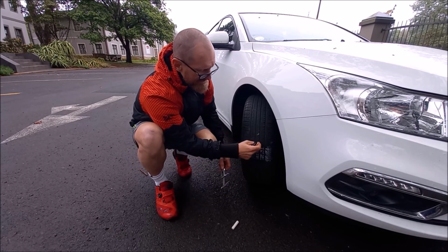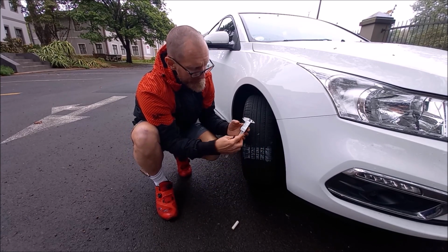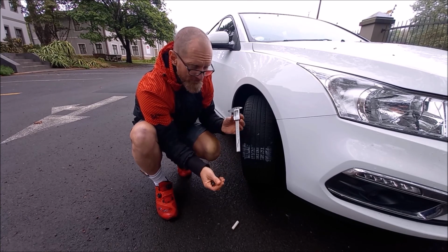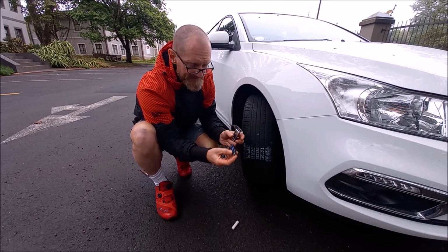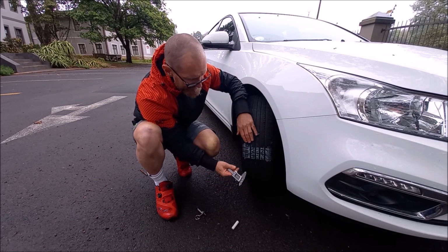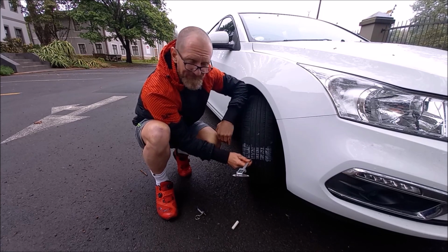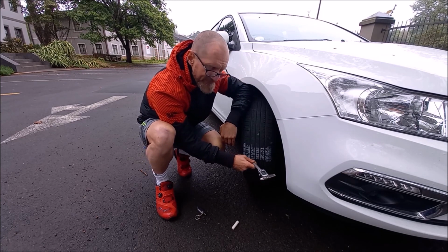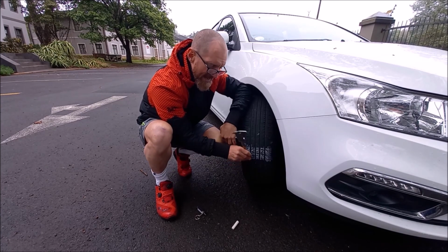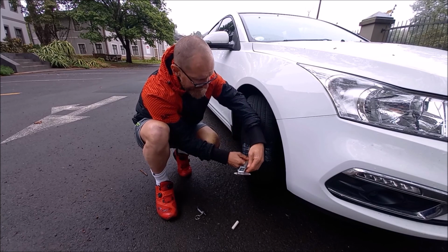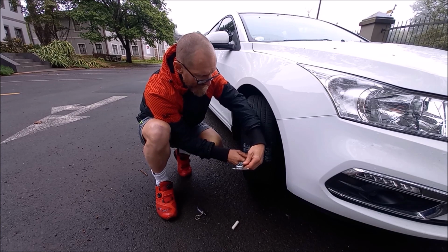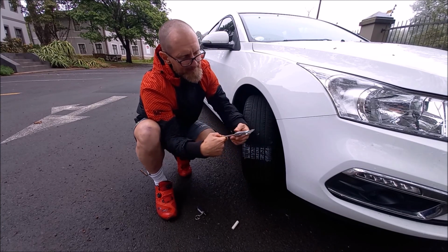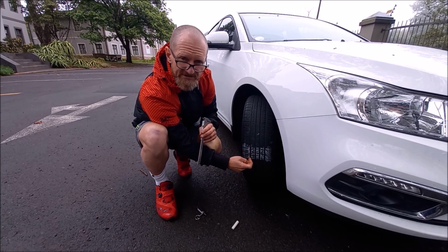Nonetheless, you can measure these channel depths either with a typical normal measuring device, which is a vernier. I tend to prefer using the vernier. However, there's various different little tread wear depth indicators that you can purchase. But in essence, you need to make sure that you measure the channel square and flat, at right angles, 90 degrees with the channel. Obviously, you get your error if you are measuring at an incorrect angle or incorrect tilt. So it needs to be square with the surface, and you would push your little reader down into the channel. So, for instance, on this vehicle, we have an outer channel depth of 2.66 millimeters. That's the channel depth on that tire.